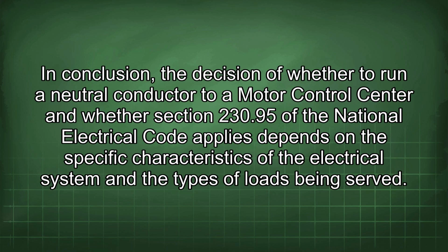In conclusion, the decision of whether to run a neutral conductor to a motor control center and whether Section 230.95 of the National Electrical Code applies depends on the specific characteristics of the electrical system and the types of loads being served.